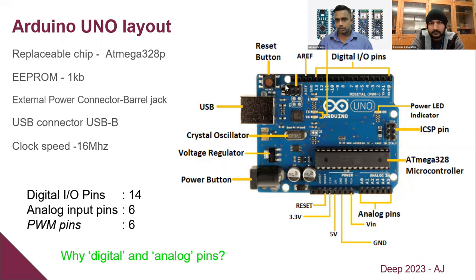And you can see these pins here, this ICSP header. This is used to program these chips separately using a different programmer, which means that if you don't want this board anymore, you can just plug in a different kind of programmer and program that chip through that programmer.